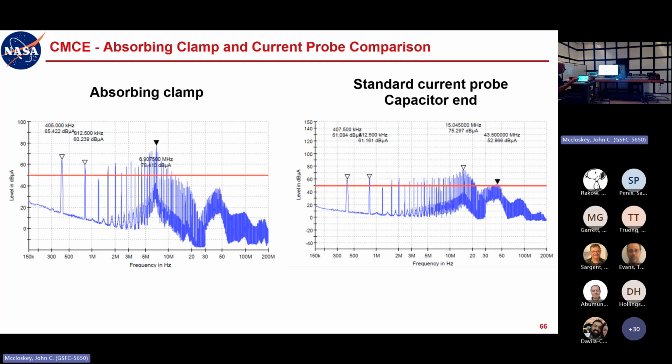That would imply that the relative permeability of that material is about 4. That seems a little low. I would expect it to be a little bit higher than that, but whatever. I'm not entirely sure what it is, but we know that it can't be 1. It's a magnetic material. We know that it's got to be something greater than 1. So again, this is the sort of stuff to pay attention to with your measurement equipment. And I think I have another chart a little further back actually that illustrates that point.